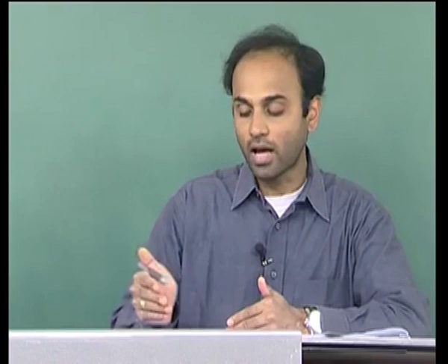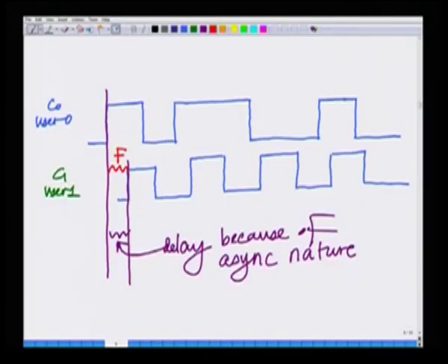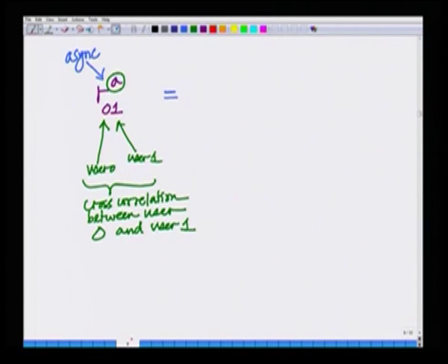As the fraction f varies between 0 and 1 to different degrees of extent, when I correlate C0 and C1, part of C0 is correlated with the shifted C1 and part of C0, the code of user 0, is correlated with the direct C1, what we had previously.